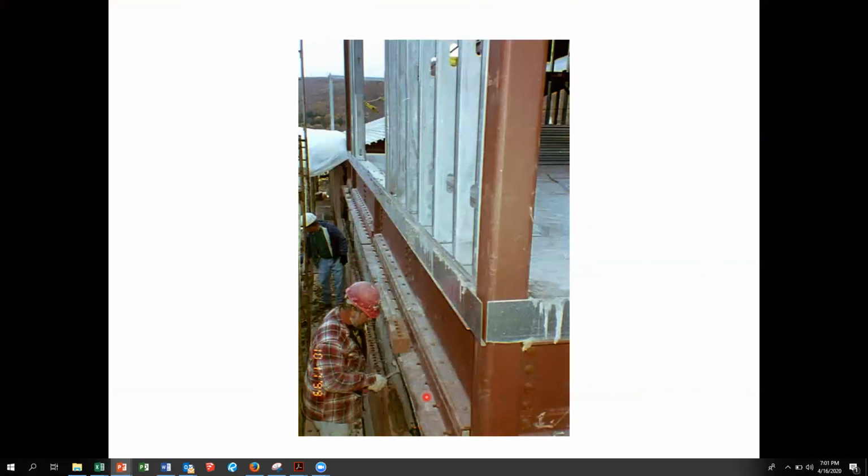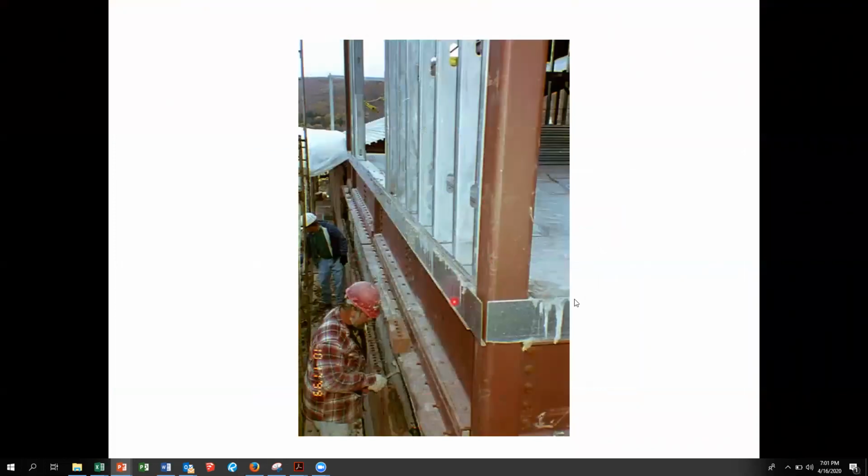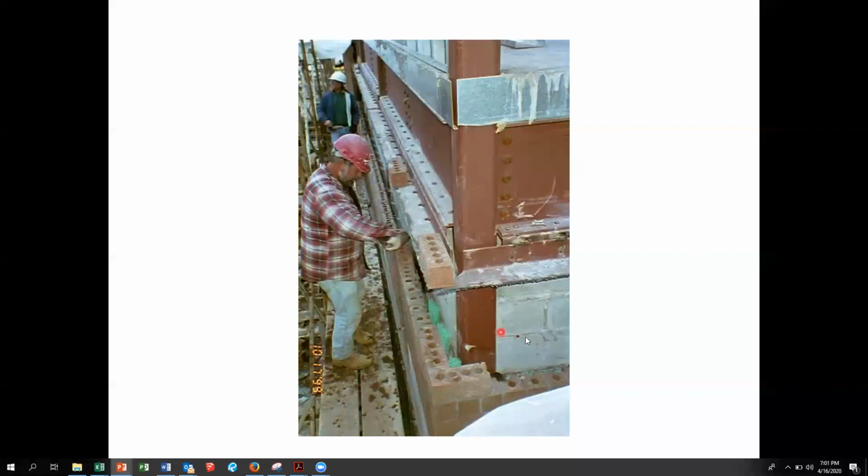Now, this down below, the brick is called the curtain wall. You're going to see a lot of this next semester. The block is called the backup wall. But once you get up to this floor level, they stopped using block. Down below here is the laboratory, so they want beefier walls, if you will, for a hands-on construction lab.